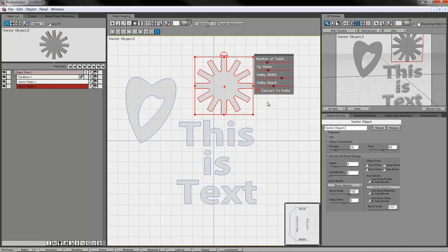Just because I've got them at this particular point doesn't mean that I can't move it backwards and forwards in space. Of course I can move it backwards and forwards in space, and I would do that by playing with the object properties. At the moment I'm looking at a camera, but I can change the object properties. So here is the object property. If I go to object mode, I can actually move this backwards and forwards in space.